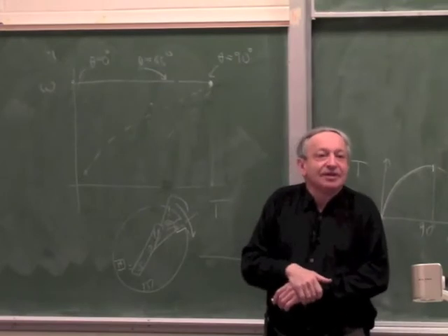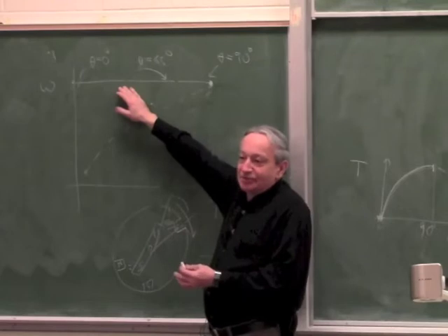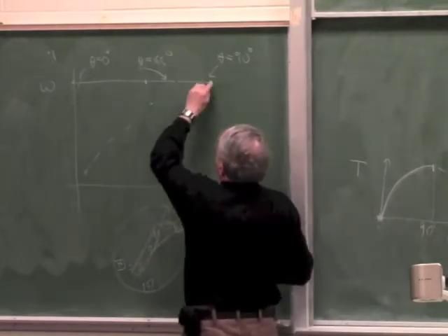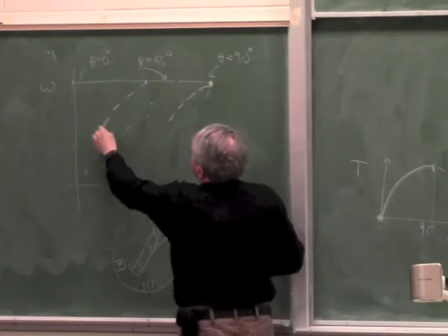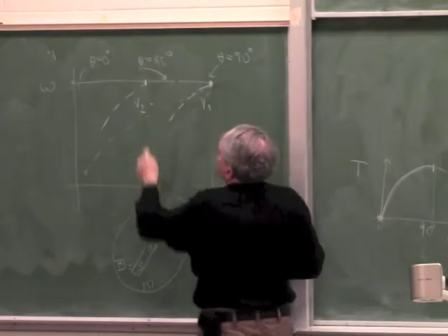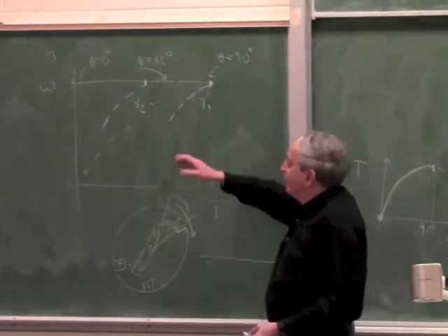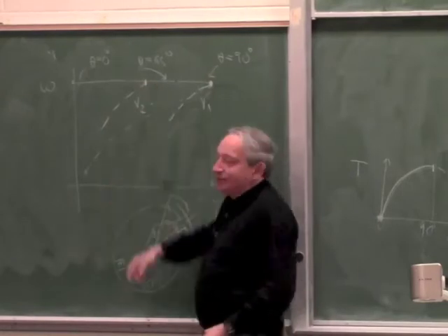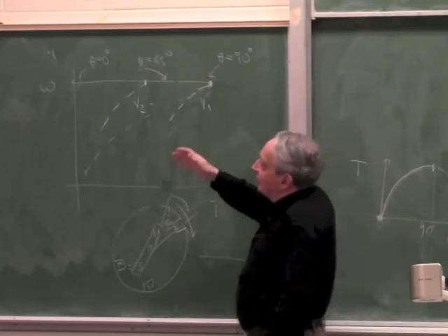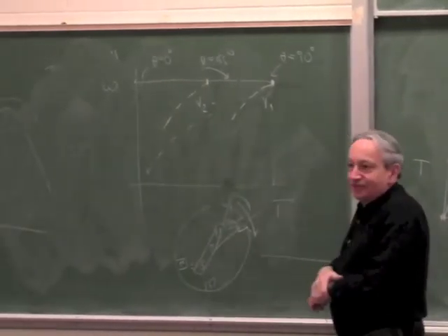Exactly, because the speed cannot change. It's a synchronous motor. All that happens is it collapses here. So instead of collapsing here, it collapses here. So this will be V1, this will be V2, because it can't generate any more torque, because there's less current, less torque. So the power angle winds up faster and it collapses. So it doesn't really have a family of curves. It just reaches a different torque and collapses.